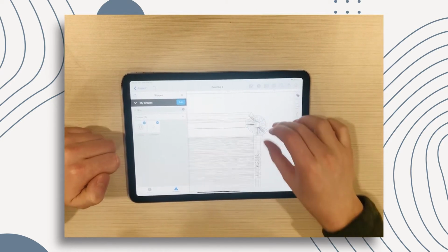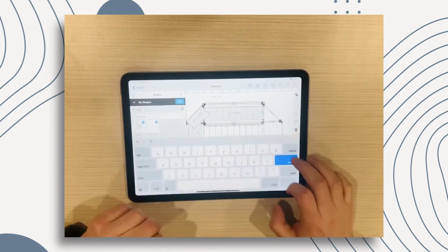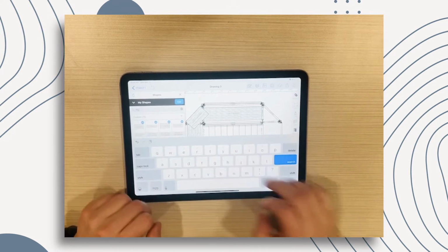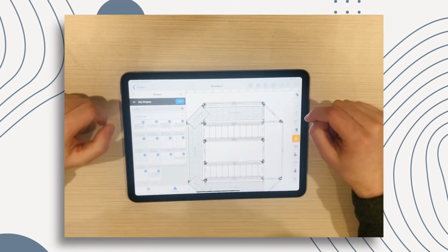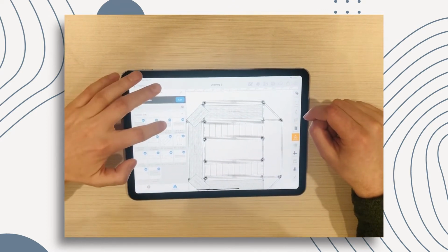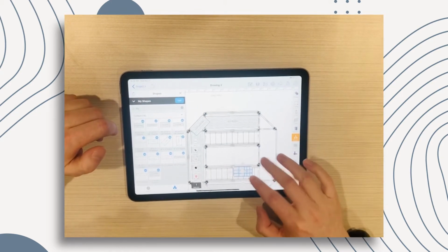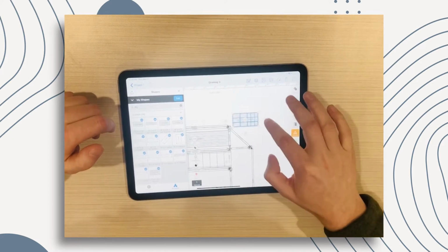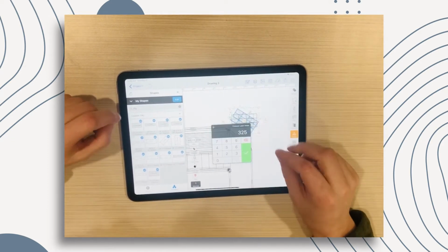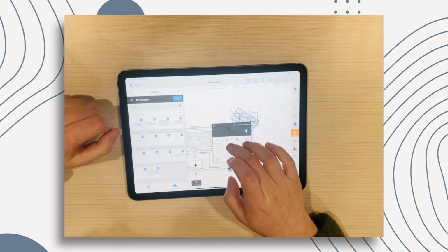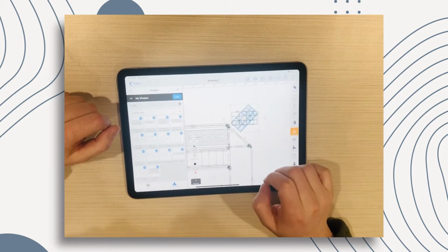It drops onto the canvas, and then using my hands, as you can see here, I can quickly move them around to assemble a complete scaffolding system. ArcSite will actually help you draw this out to scale. There are different snap points on these different objects, so they connect to each other in very fluid motions. They can also be rotated or manipulated, as you can see me doing here.